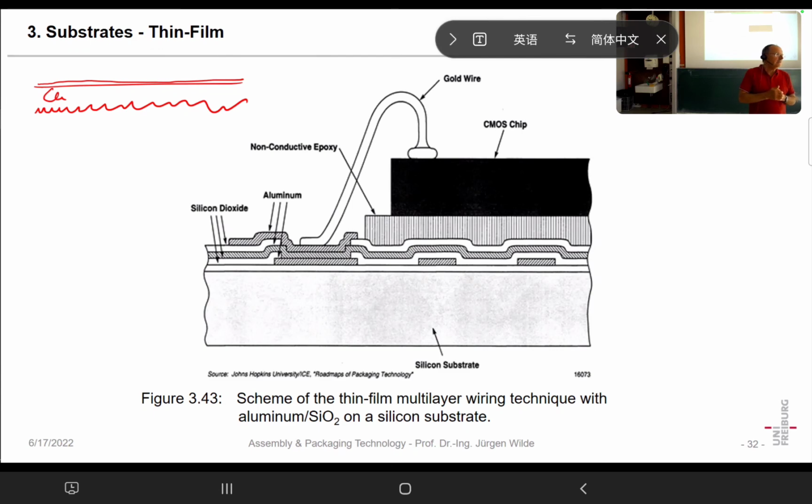Also, a thick film circuit is not extremely smooth on the top side. That's evident for multi-layers, but also on the top side, as it is a printed material, we still see, for instance, the screen pattern even after the firing. Also, there's always a certain roughness on a thick film circuit. And so people were seeking for the perfect conductor, which is as smooth as possible.